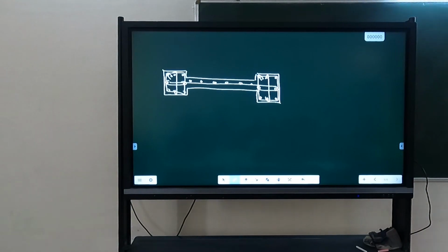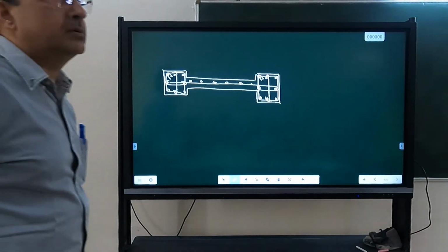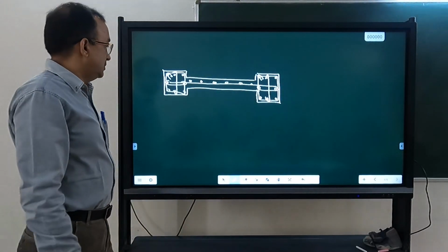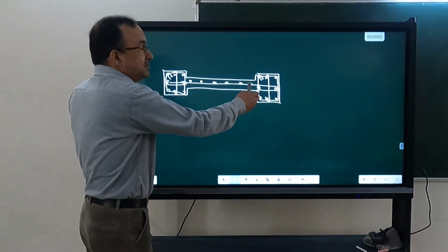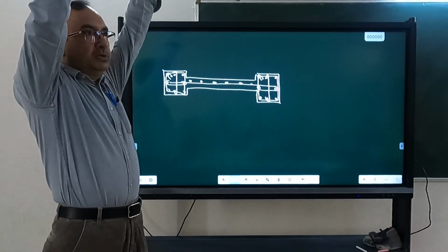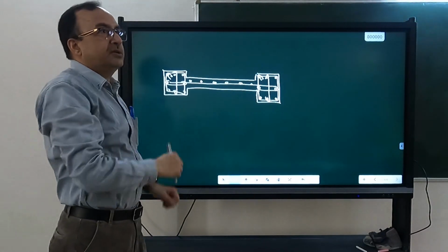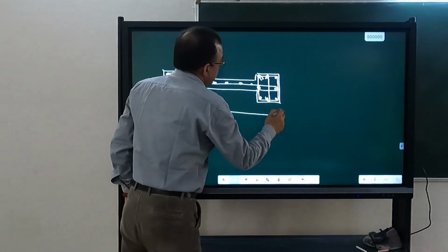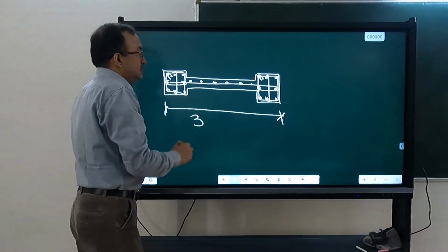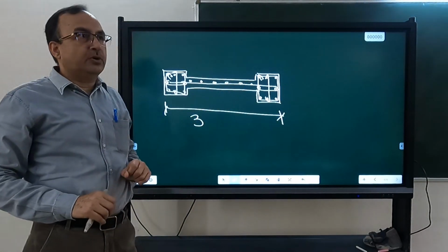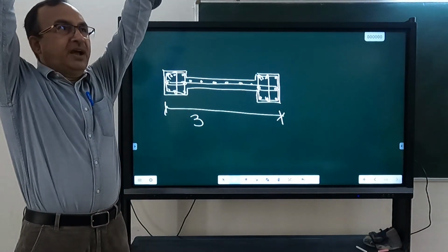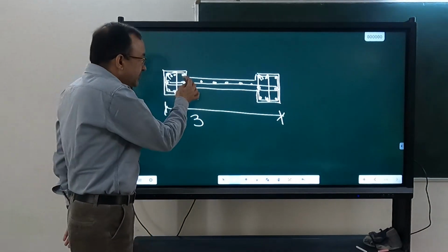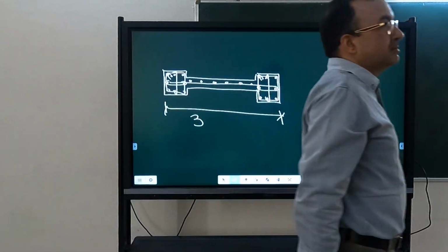This whole assembly will become a section. Yeah, this is a section of a shear wall. Here it may appear very large, but when you talk about a 15-story building, then it's not that large as compared to that height. Suppose this length is 3 meters, so it will look large from the point of view of a column. But when you consider 45-meter height also, then this will not appear to be very large. It is a cylinder system, and plane sections will almost remain plane.